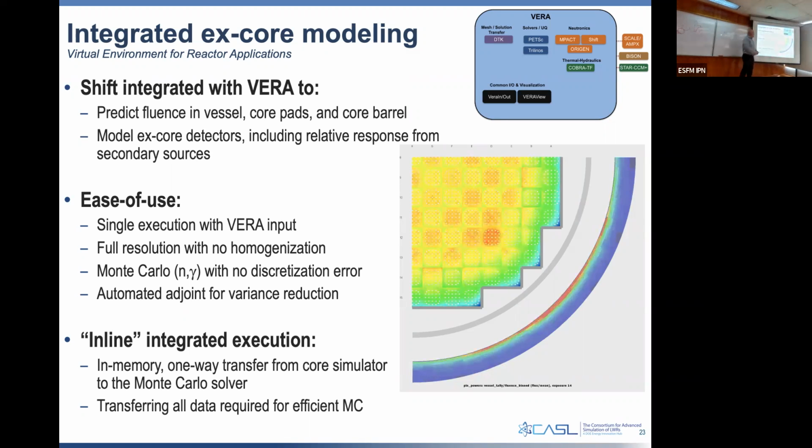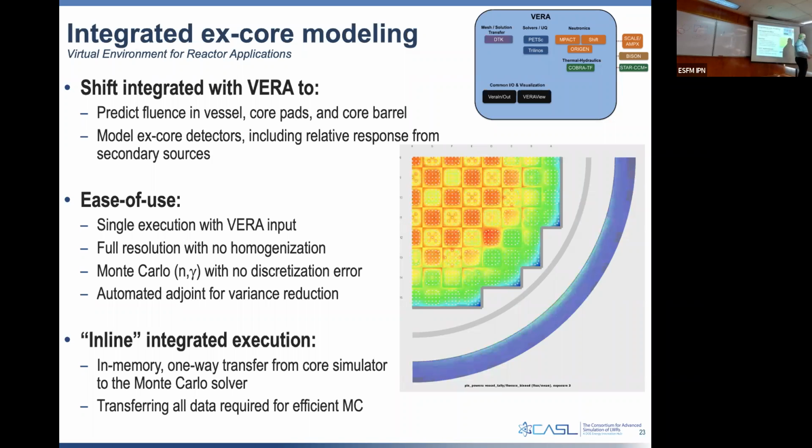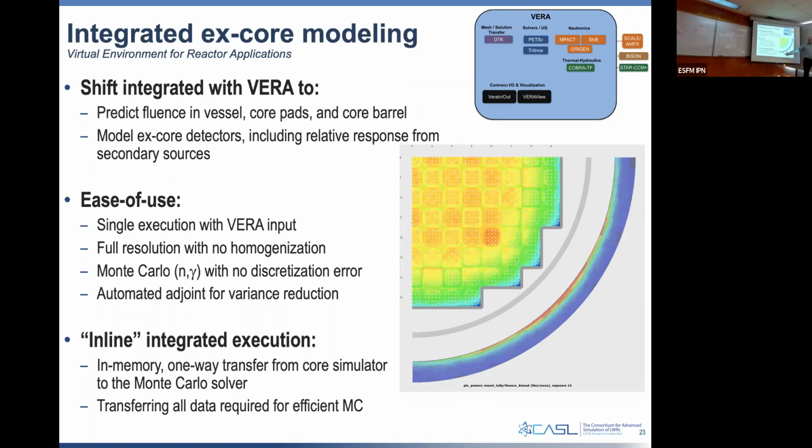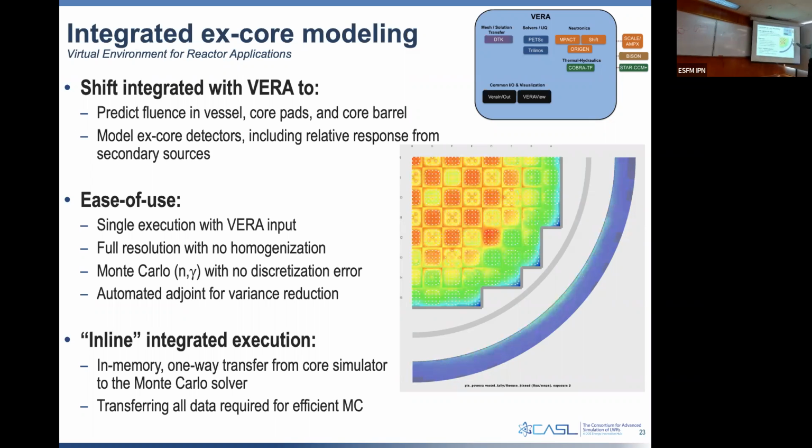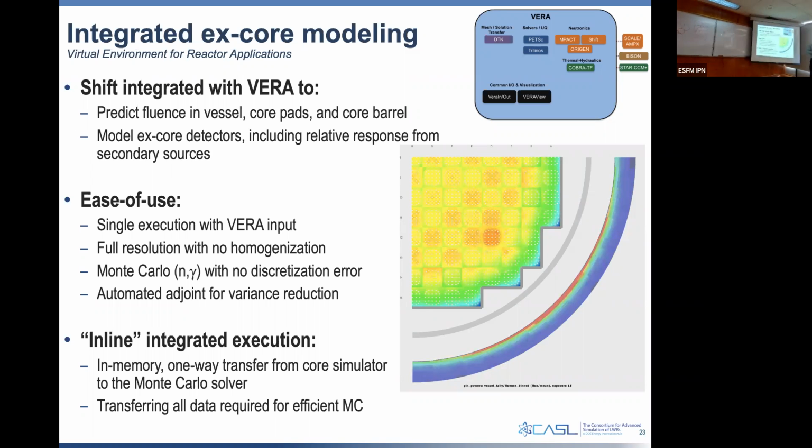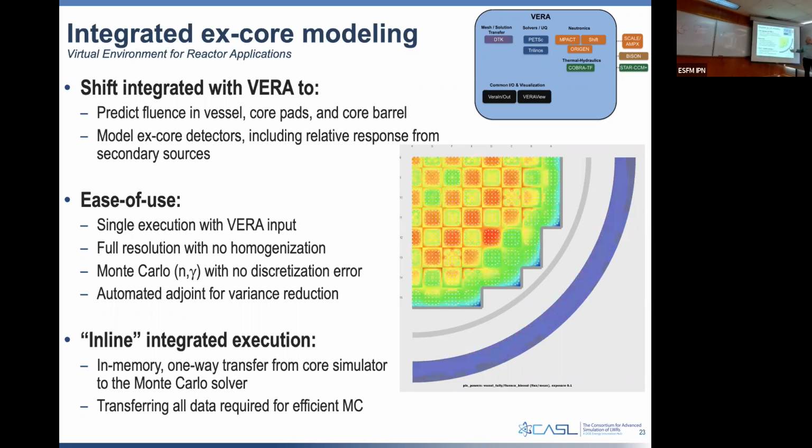And it can do the radiation transport all the way out here to this vessel. And if we model this over the 18-month fuel cycle, we can see how much irradiation has been added to that. And all of that irradiation out there is starting to weaken that pressure vessel. It's very little, but over the course of 60 years, it can be significant.